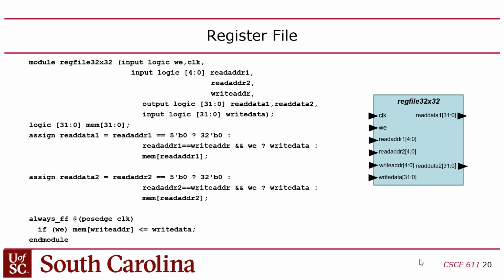Okay. Yeah, so what she's saying is that these inputs and outputs have logic on them, right? Sometimes you don't need that logic. Actually, you don't need it on any inputs. So the fact that I say input logic is kind of redundant. You can just say input, right? But output logic is needed whenever an output is driven by an always. What does that matter? I don't know. It's a weird holdover from Verilog.